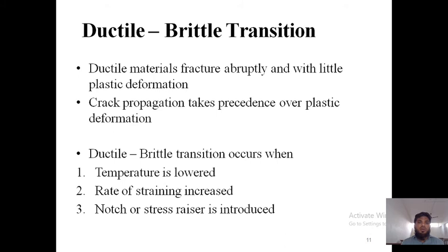But when the material converted to brittle, as soon as it got hit by an iceberg, it underwent a brittle fracture. Because of that fracture, as it had already converted to brittle, even one small crack propagated through the whole material, and the whole ship went down. Okay, the whole ship was drawn into the sea.